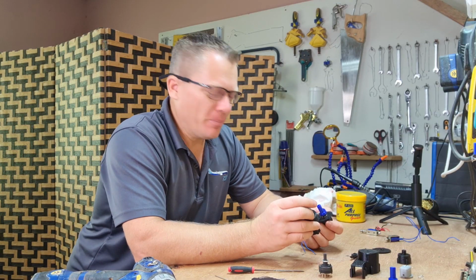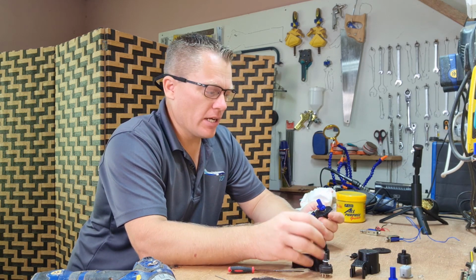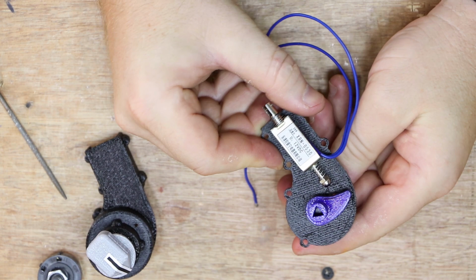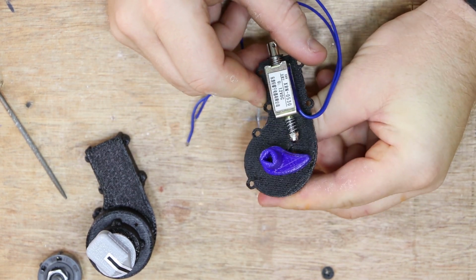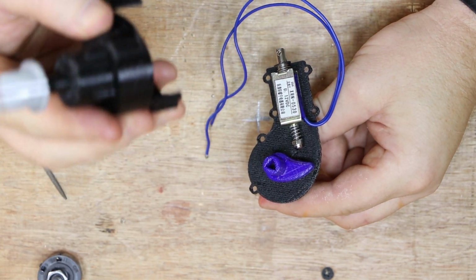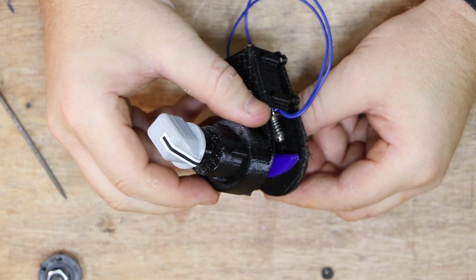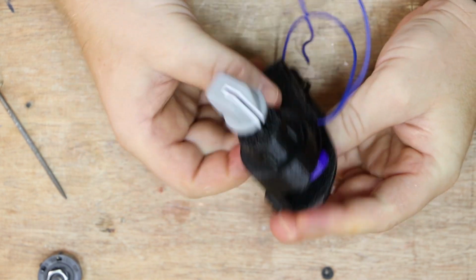Now the important part of this is to make sure that the activation cam is 1 notch up into the off position, so it should be around about there, just off the solenoid, again by about 8mm. Our general knob in the upper body is in the 12 o'clock position. Put the 2 parts together and they should align perfectly.